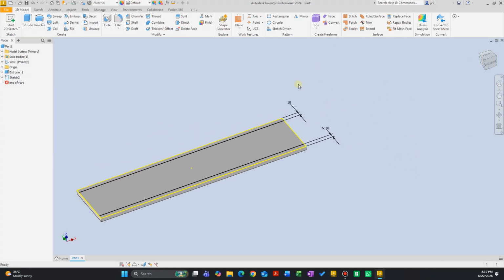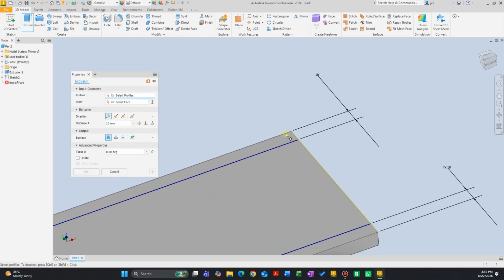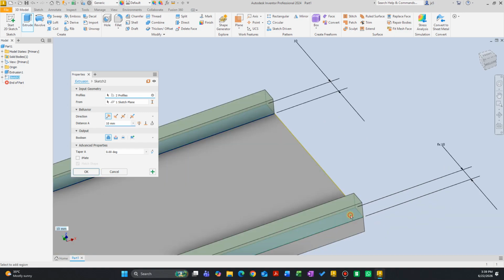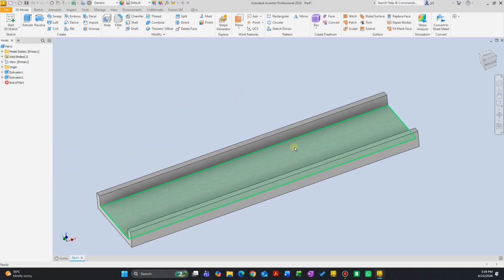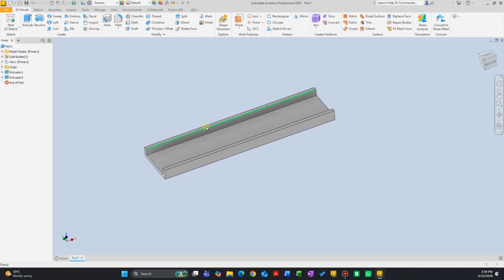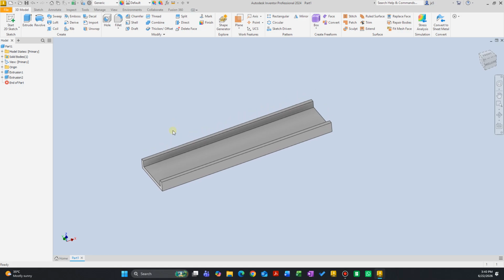Now let's finish the 2D sketch, right click, extrude, and select this top section and this bottom section. Let's say this is 20 millimeters tall. I'm sure you're already thinking you could have used so many different ways to do this. You could have drawn smaller rectangles and used the mirror pattern. You could have just done one wall on the top side and mirrored that. There are so many different ways to do this, but I intentionally did it using the lines because I don't think we've done that before. It's a very simple way to do it. So this is our first part.